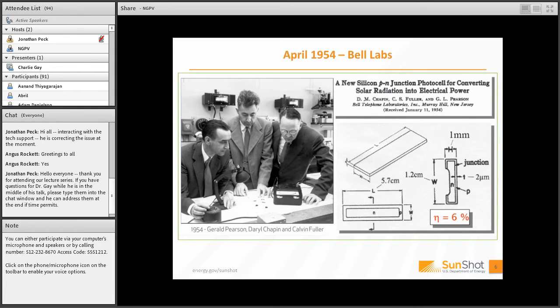The ingot was sliced lengthwise into a long thin slab, and a wraparound contact cell made on N-type silicon. And as all of you likely know today, P-type is the most common base material with an N-type diffusion, phosphorus diffusion on a boron-doped base wafer. Cells at that point in 1954 were about 6% efficient.